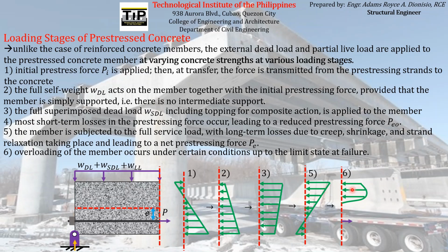So this is the stress diagram at impending failure, wherein the concrete element has already experienced cracking, because the stress here tends to have lesser and lesser magnitude until it reaches a tensile stress. After this stress reaches the maximum tensile stress that can be experienced by the concrete element itself, it will produce what we call cracks.